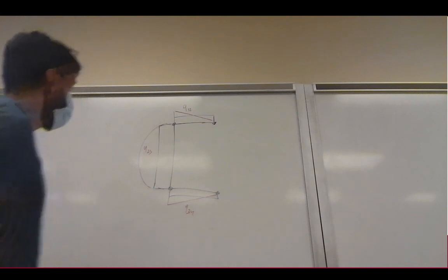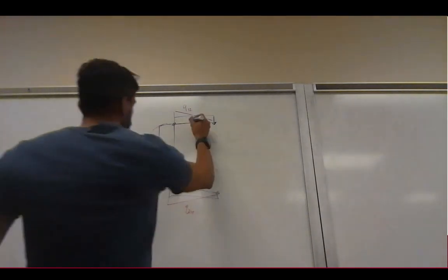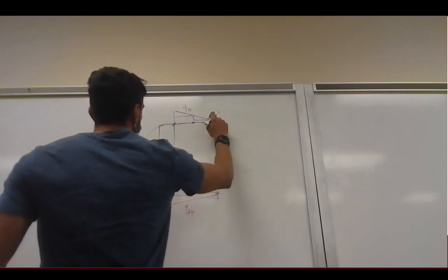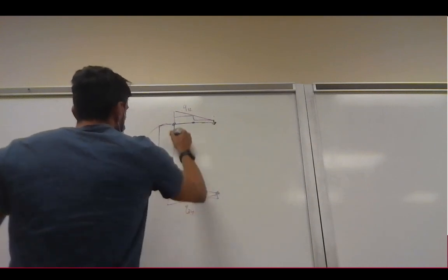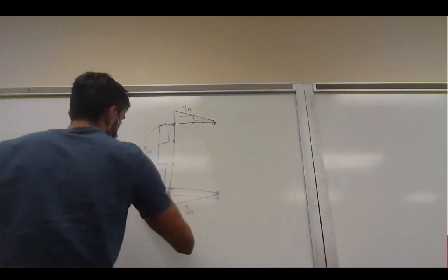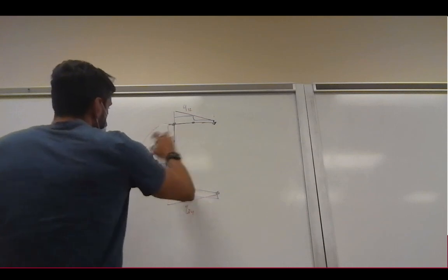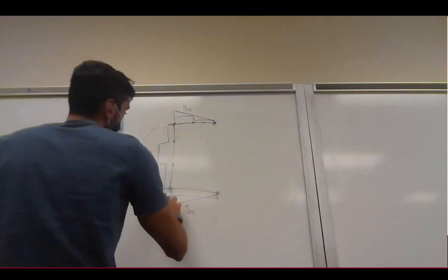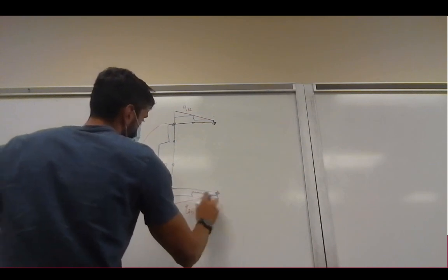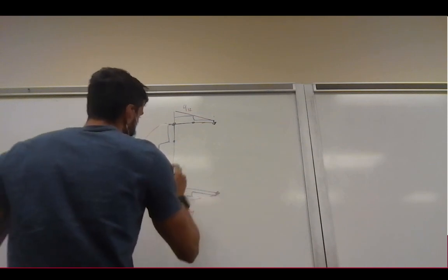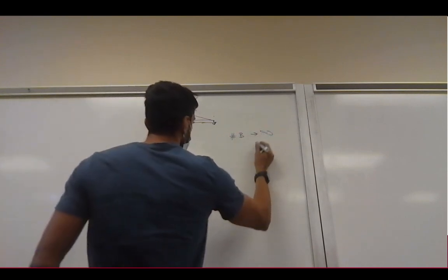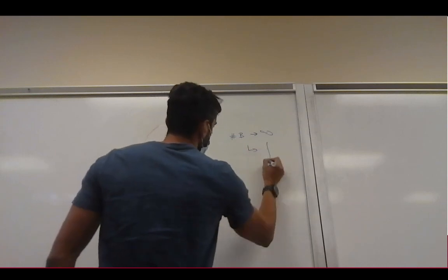Okay, so that's it. And of course, then you can go ahead and say, well, if we add an extra boom area, then I get a stepwise shear flow, so I can get closer to what my true shear flow would be. And if I add enough booms, then you get close to your actual shear flow. So if your number of booms goes to infinity, then you basically go to the integral format again.